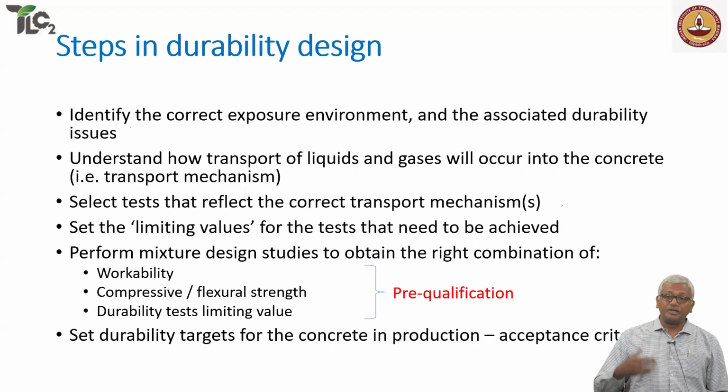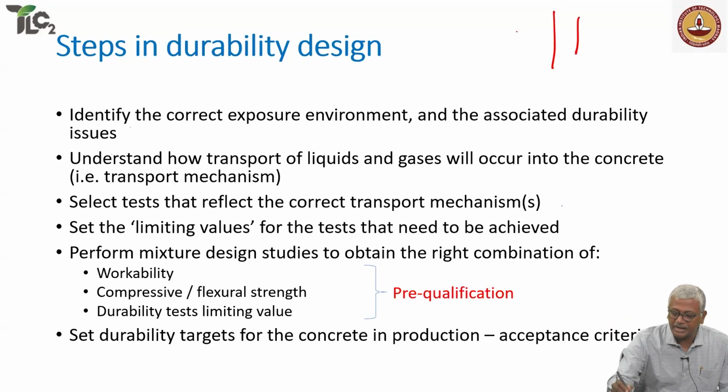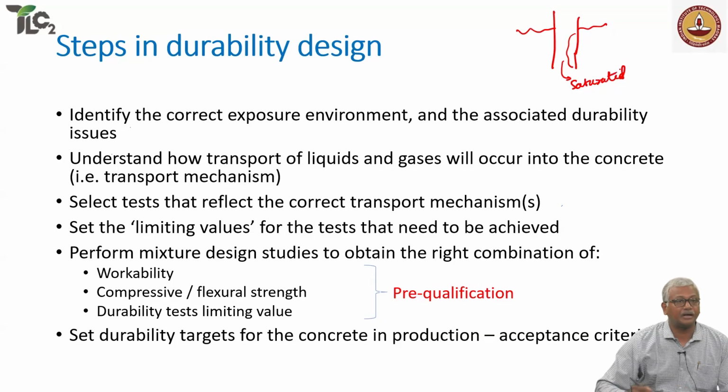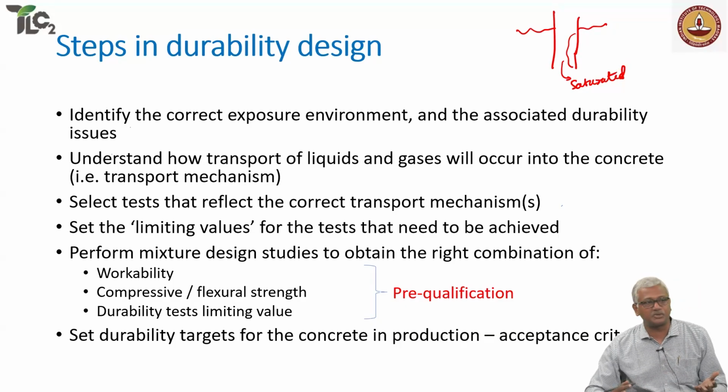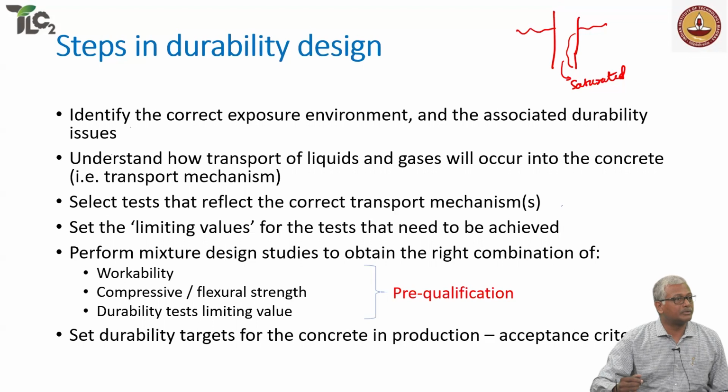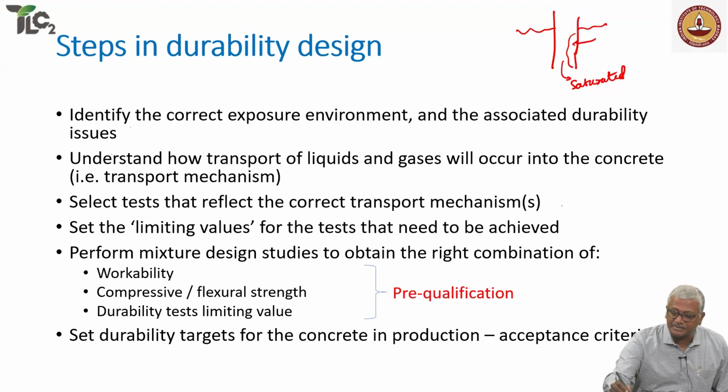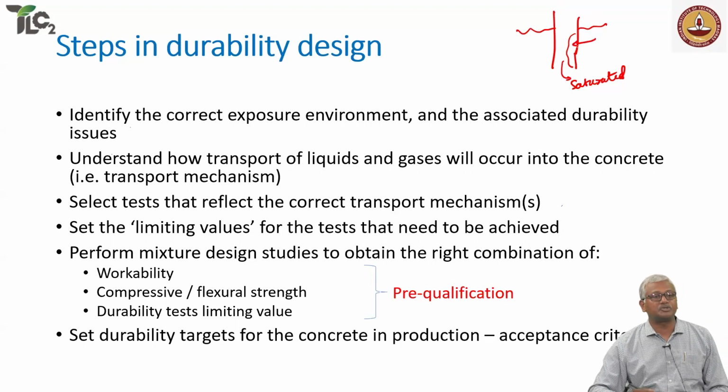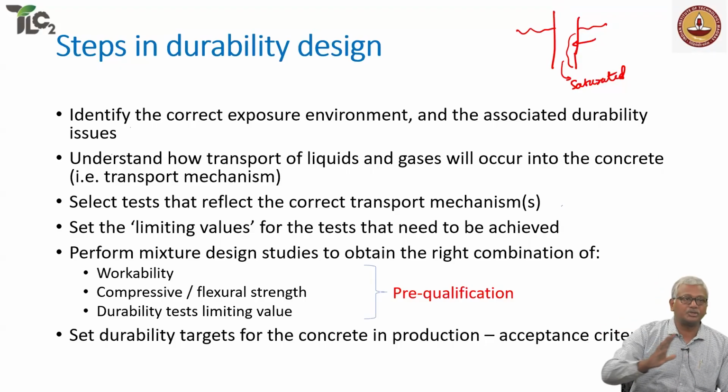Is it by diffusion? Like if you have a column standing in seawater, right? Here the concrete is completely saturated, right? Under the water level, concrete is completely saturated. So there are driving mechanisms of the liquid into the concrete which involve penetration due to pressure.